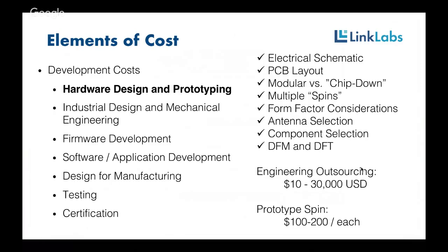Multiple spins. This is where the hardware designer and the team, especially when you're dealing with radios and complex enclosures and power requirements, often have to spin the physical PCB multiple times as the prototype progresses through its life cycle. I don't think any IoT product in history has ever been launched on a single spin unless it's just a derivative of an existing design. We often see 2, 3, 4, 5 spins of prototypes before customers and products are a great fit for exactly how they want to go to market. And every time you do that, it adds cost because spinning prototype hardware is always expensive.